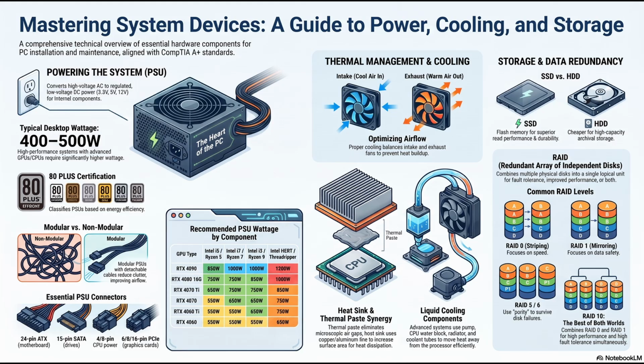Not to mention the biological threat. Yes. Warm water combined with light from case LEDs is a perfect breeding ground for microscopic algae and bacteria. If you do not use proper biocides, your loop will grow a layer of green slime that clogs the microchannels in the CPU block, ruining the system's ability to absorb heat. So you get unparalleled performance, but you have to become a part-time plumber, chemist, and biologist to maintain it.